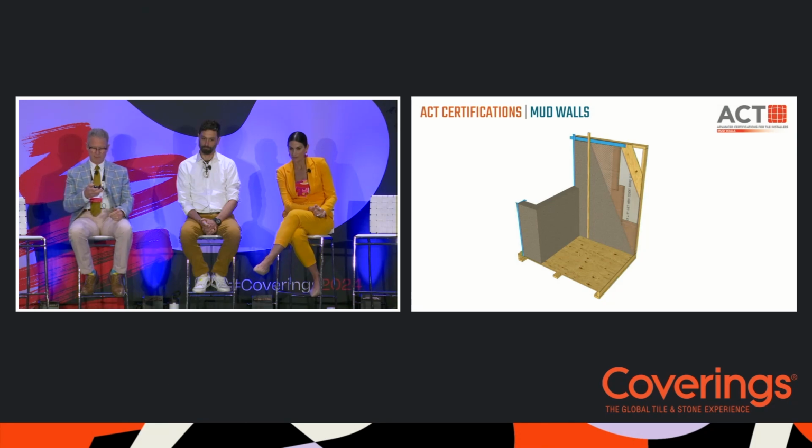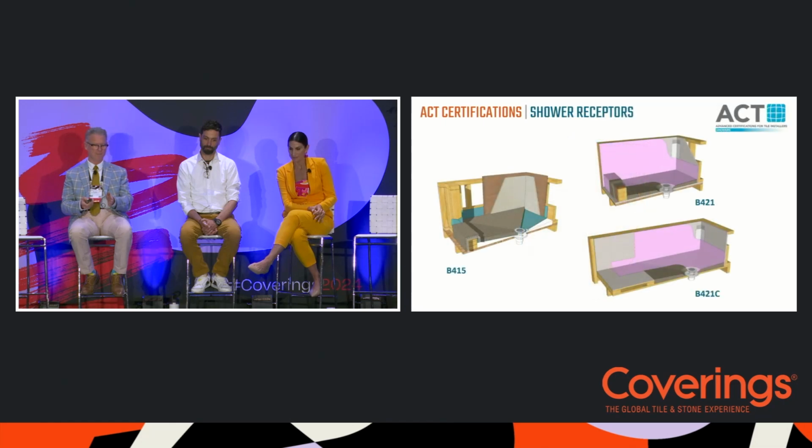On that inside corner, there has to be a break in the mud because that's an expansion joint. We haven't talked about expansion joints today. This may be the first seminar that we haven't, because expansion joints and substrates, those are two areas that seem to go wrong a lot. But in any case, that inside corner, they're evaluated on their ability to keep that clean, to allow independent movement.